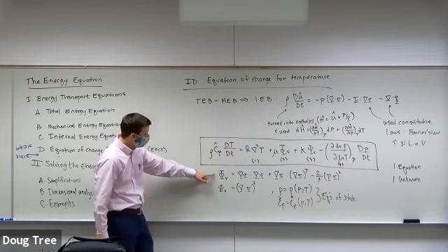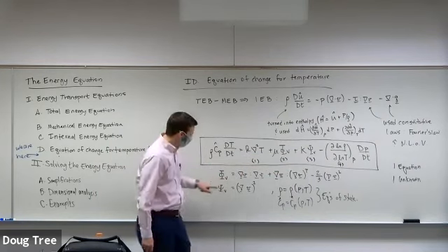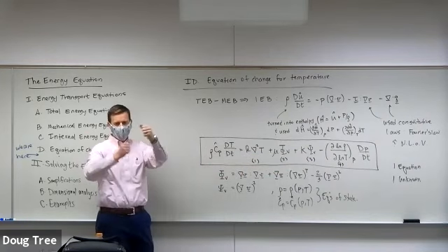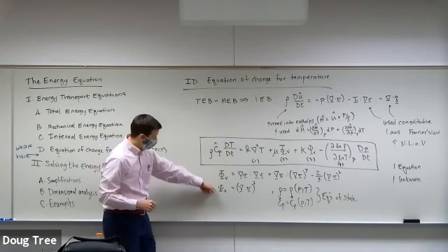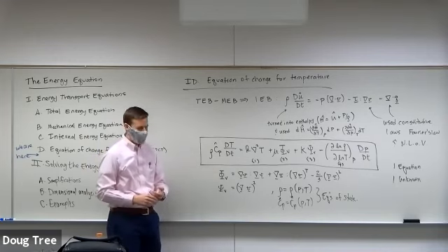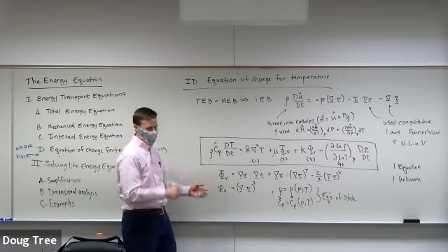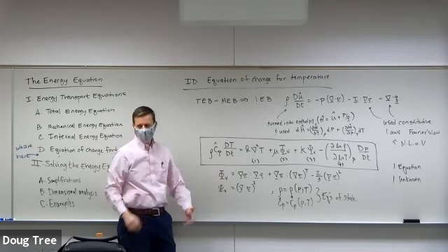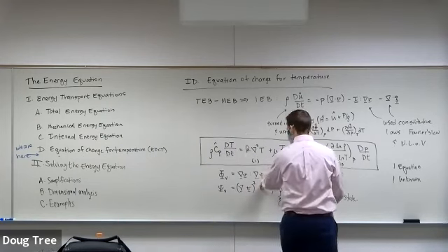The capital phi has the grad V double dot grad V parts, so that has all of the off-diagonal parts of that matrix. And then del dot V is the trace, the sum of the diagonal parts. This is volume expansion squared. This is essentially all the shear components on the other parts squared.